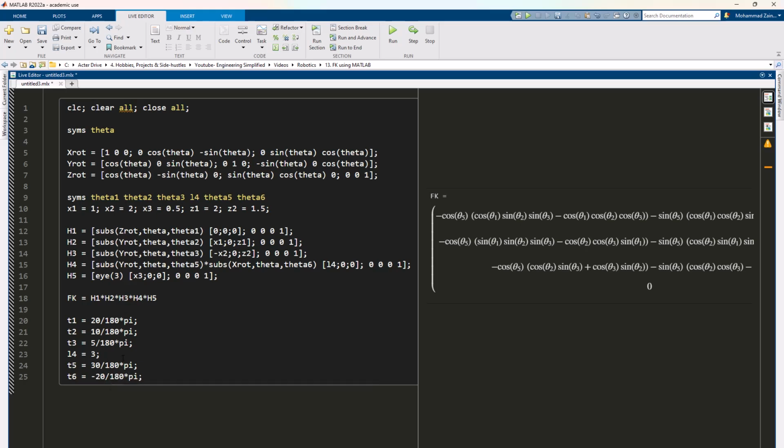Okay, so he has given me all these robot parameters. He says, you have the robot right here, and I want you to make the robot achieve these values of theta 1, theta 2, theta 3, A4, theta 5, and theta 6. So now all you would do is go into the software of the robot, input these values, and it would make the robot move and achieve a specific orientation and position.